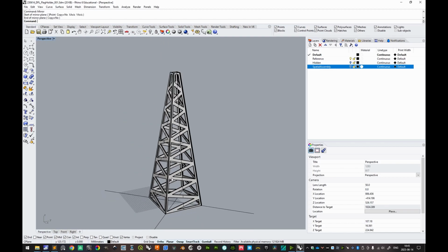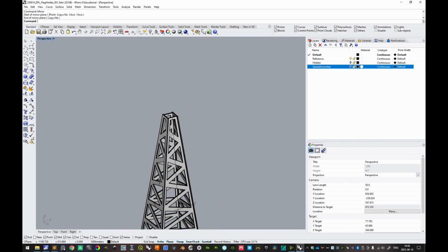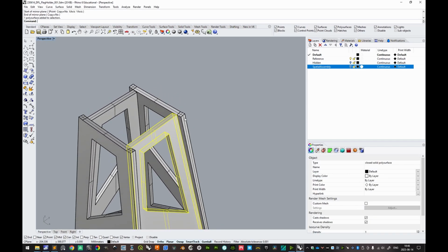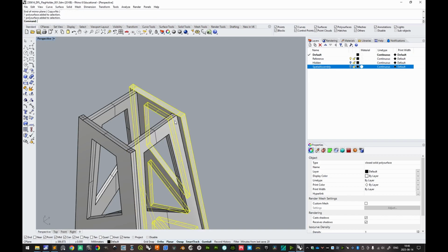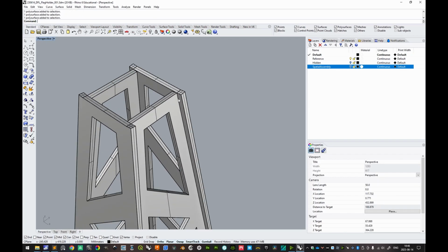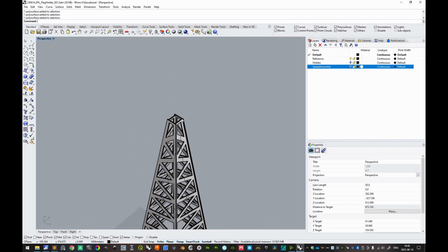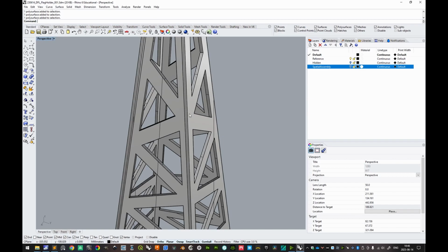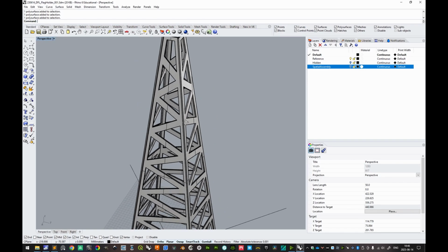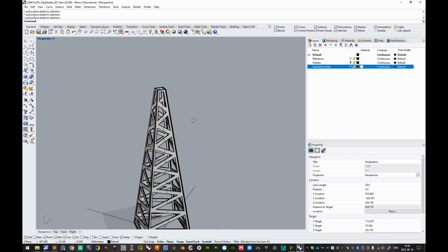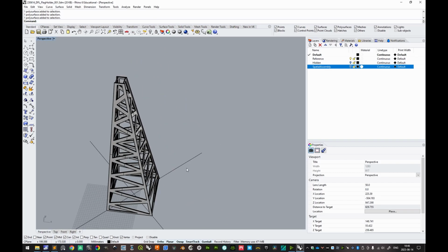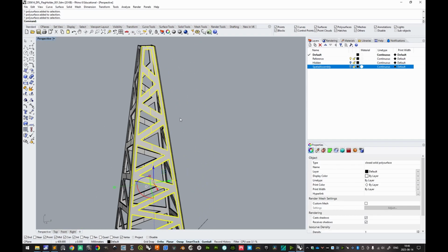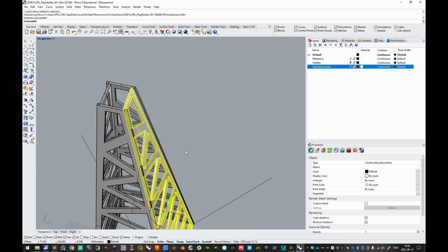And now we want to make sure that this object is assemblable in a practical way. As of now, you would have to glue this, and it would be tedious and hard to achieve this level of exactness. But if we do sort of an outset and a hole for that outset, then I think it's easier to assemble. So what we can do is to select one side here that we want to have as our first. Yeah, we can do this one, the one that is oriented toward the X positive here.